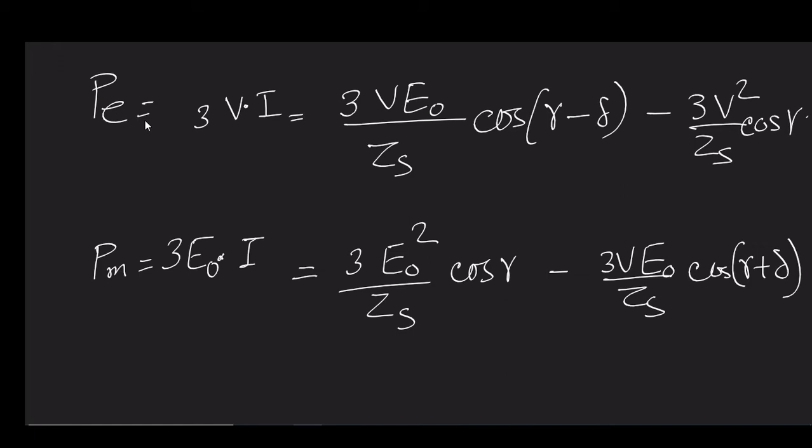Now, if you consider the magnitudes of E and V, in most cases they are almost proportional. So, if you are keeping your V at a rated level, you can expect that for rated current also, the difference between E and V will be very small.